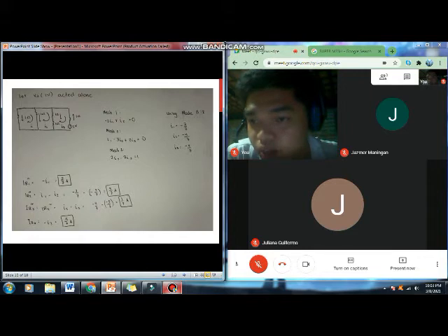So, move on. IR sub 2 for the fourth prime: I sub 1 minus I sub 2 is equals to negative 2 over 7 minus the quantity of negative 4 over 7 to get the answer of 2 over 7 amperes. IR sub 3 fourth prime is equals to IR sub 4 fourth prime. So, parehas lang sila ng value. So, to get that, I sub 2 minus I sub 3. So, the value of these two, ay minus natin sila. Negative 4 over 7 minus the quantity of negative 5 over 7 is equals to 1 over 7 amperes.